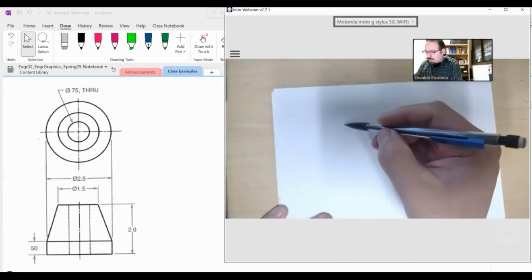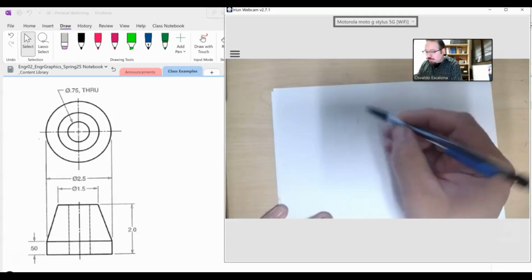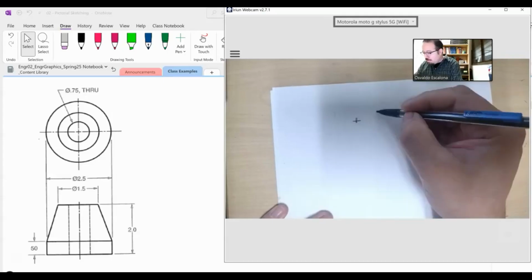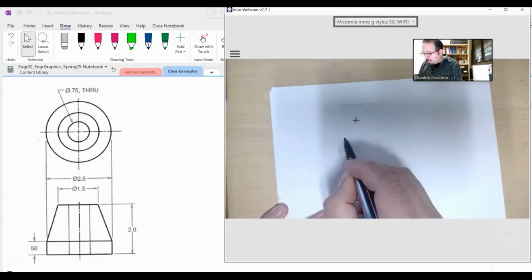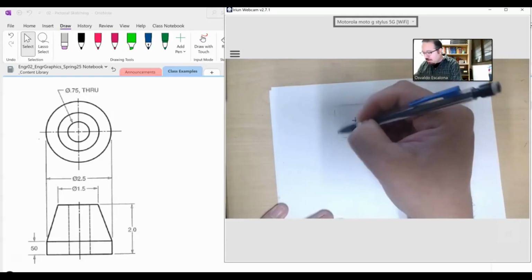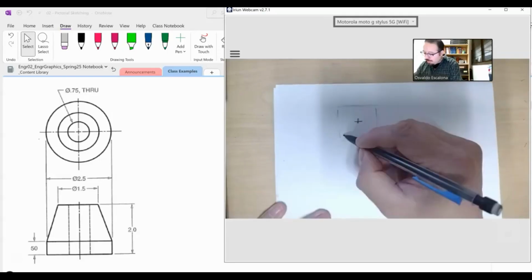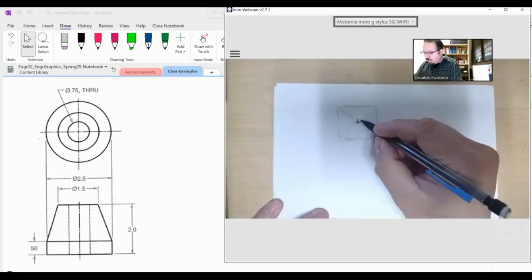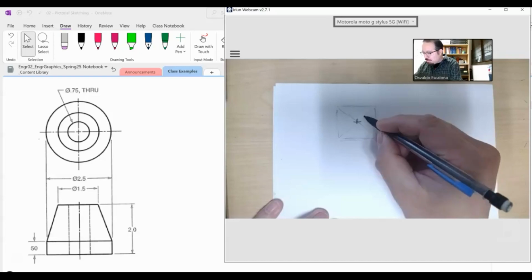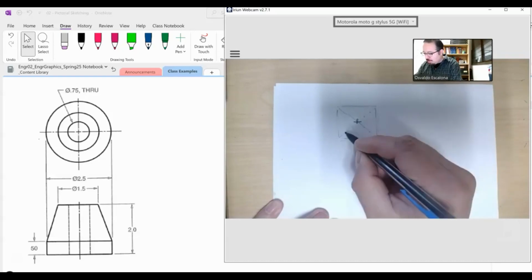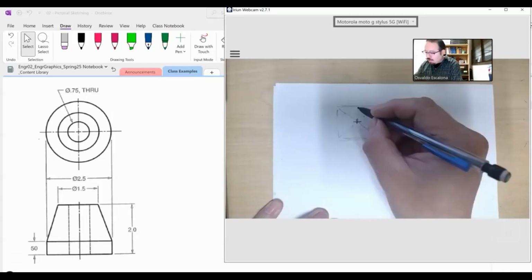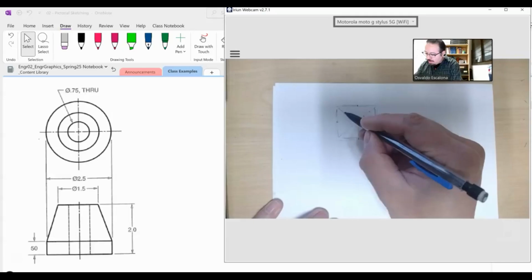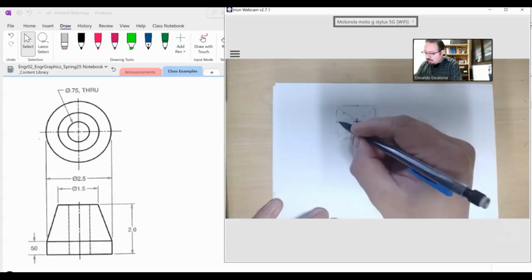The way you make a circle is, let's say that this is my bullseye, right? My bullseye is where the whole center is going to be. Step number one, you make a box. So let's say box about there. First make a box. Then you make a diagonal, and then you make another diagonal. And then this piece right here, you split it into three parts. 1, 2, 3, 1, 2, 3, 1, 2, 3, 1, 2, 3. Then the top was here, the other one was there. Boom, boom, boom. And then you connect this one with the 2/3 away, and you create an arc.